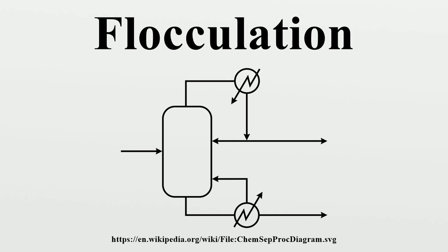Jar test. The purpose of this test is to select types of coagulant and also to estimate the optimal dose needed in removing the charged particles that occur in raw water. Jar test is an experiment to understand the processes of coagulation, flocculation, and sedimentation. Jar test apparatus consists of six batch beakers, equipped with a paddle mixer for each beaker. In a standard practice, jar test involves rapid mixing, followed by slow mixing and later the sedimentation process.